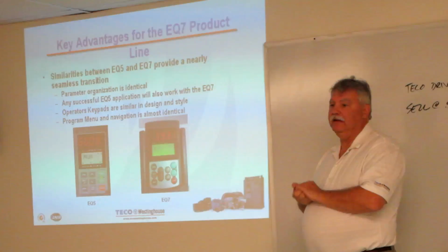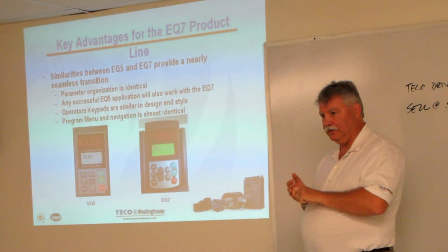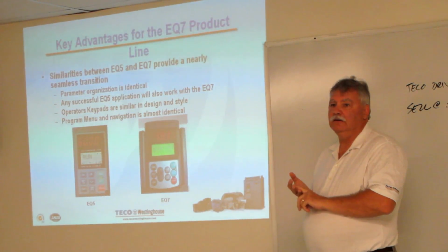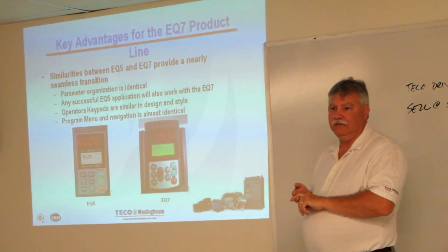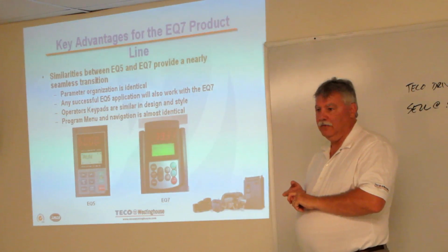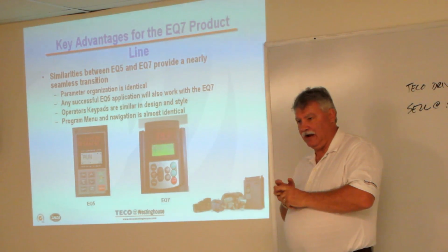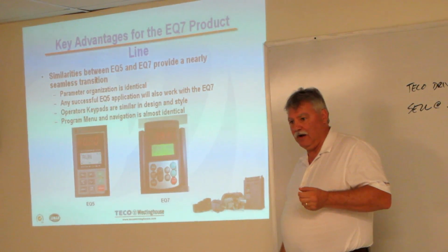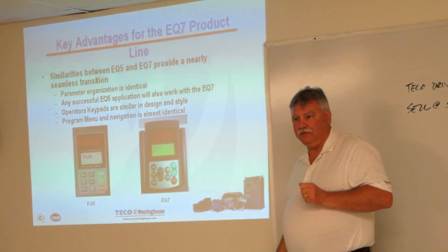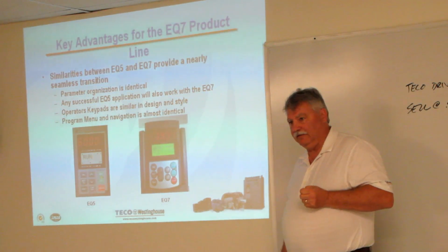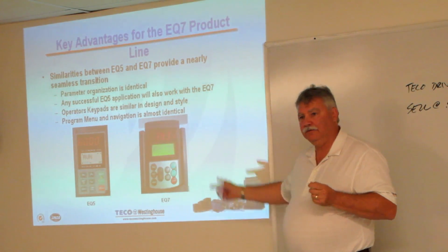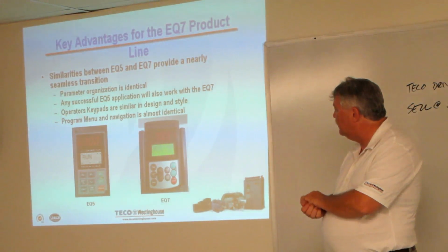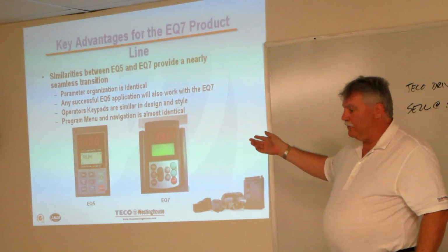You have a variety of screens for diagnostics, so you can look at the state of the I/O and see it respond directly on that. You can look at any analog inputs and see what they're doing. So if you're not getting a feedback signal over and the drive's not responding right, is it because the drive's not set up properly or because the signal's not coming in? You can go to a screen and look at the signal coming across and see if you're getting any changes in response. So those are the type of things.